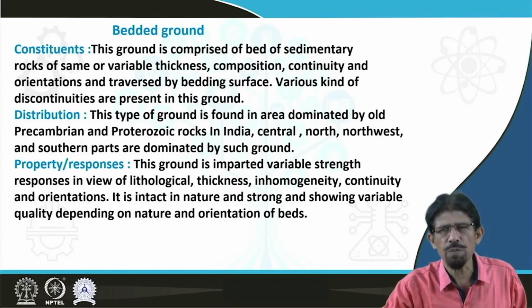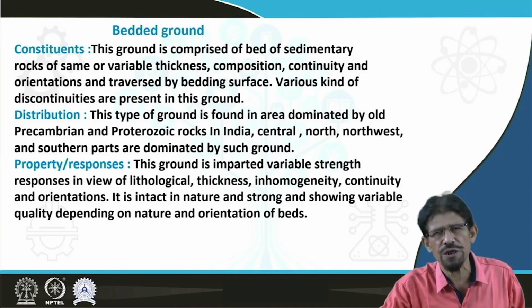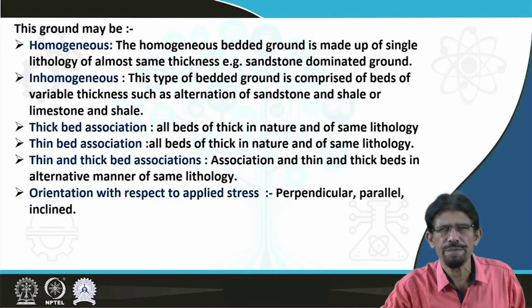As far as property is concerned, because there is variation in thickness, variation in continuity, variation in lithology, variation in orientation, therefore the strength and hardness as well as durability depend on continuity, thickness, nature of strata and orientation of bed.